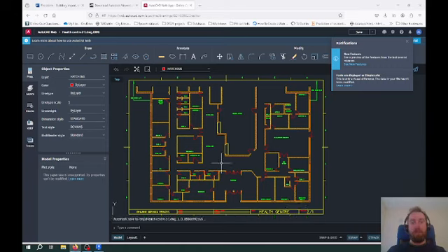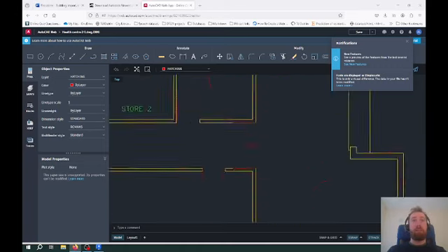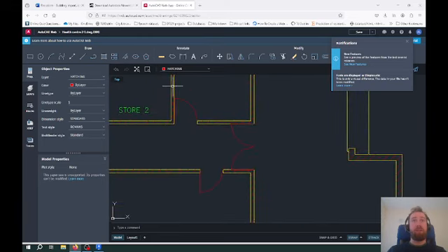So I'm just going to open up the drawing again here in CAD, and we'll see that if we zoom in on that same door and we measure across the door, according to the AutoCAD, this is 15 units wide for a door. That doesn't really mean much to us because we want it in an engineering unit like millimeters. So we have to scale our drawing based on that information.